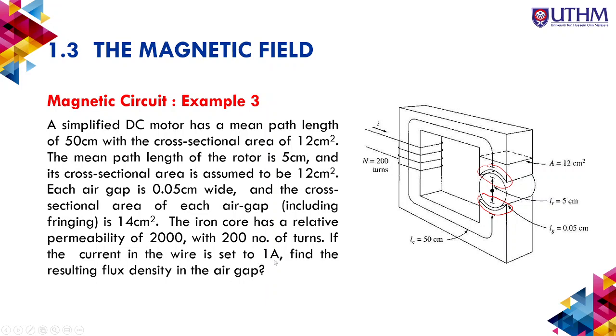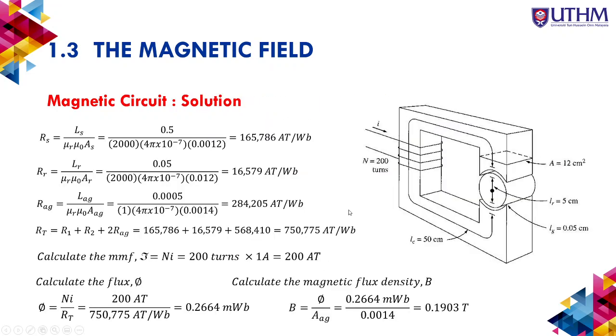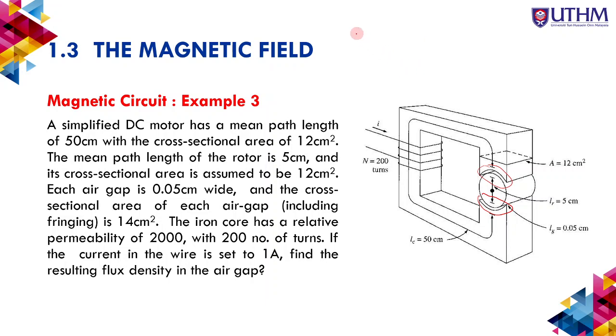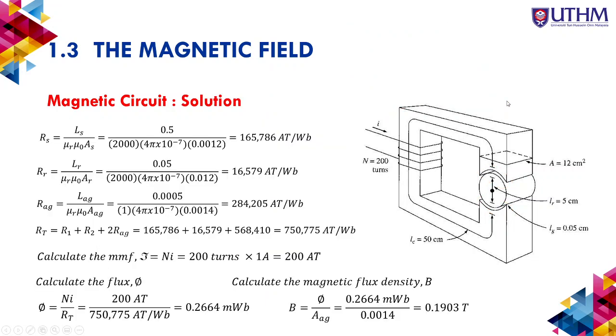I think better we start from the magnetic circuit. We have the MMF, and then the reluctance of the core, RC, then the reluctance R1, and then air gap 2. So we have a total of 4 reluctances: our core, air gap 1 over here, then the rotor, and then the second air gap. The air gaps are already combined.